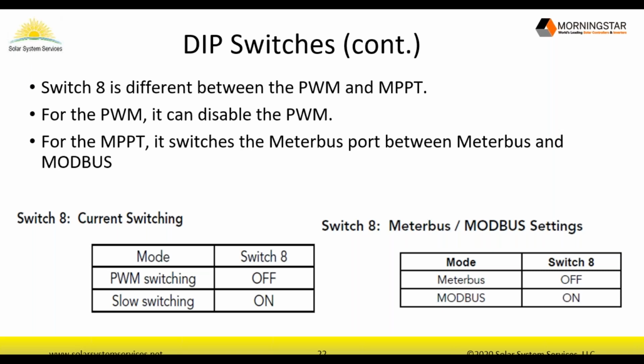And I think the normal switching, and Brad can correct me if I'm wrong, but I think the normal frequency switching on the PWM is rather low. It's in the few hundred hertz range or something like that. Yeah, it's slow 300 switching, actually, 300 hertz. Yes, I thought it was 400, but okay, 300 in that range. Slow switching is basically 1 hertz. So that means you've gone from 300 hertz to 1, which is every second.